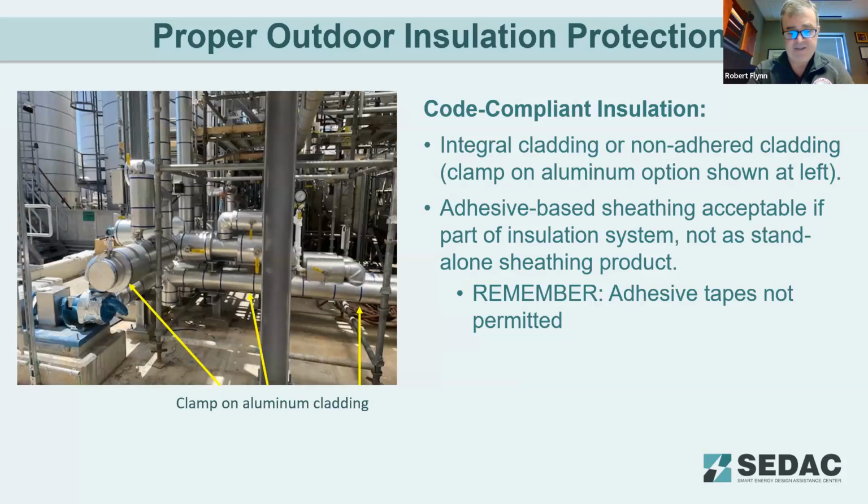So the next one is continuing on proper outdoor insulation protection, code compliance insulation, integral cladding or non-adhesive cladding, as Sean stated. Adhesive-based sheathing is acceptable if part of the insulation system and not a standalone sheathing product. Remember, adhesive tapes are not permitted.